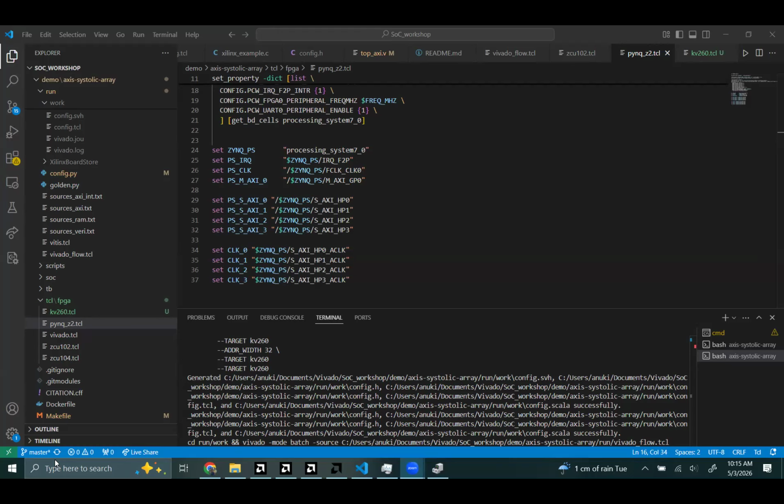So I want to keep the Tcl scripts as minimal as possible in my projects, which is why I integrate this open source IP in Verilog itself. That way you can pass down parameters easily. In Tcl scripts it's much harder to pass parameters; you have to give the same parameter to every different thing, and you can't send parameters from Verilog to Tcl very easily. So you have a bunch of issues like that.